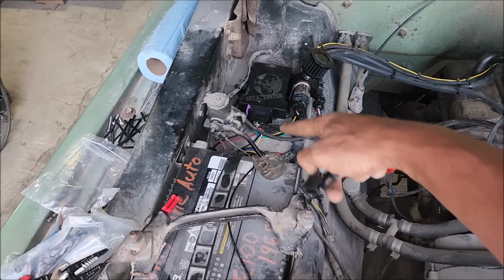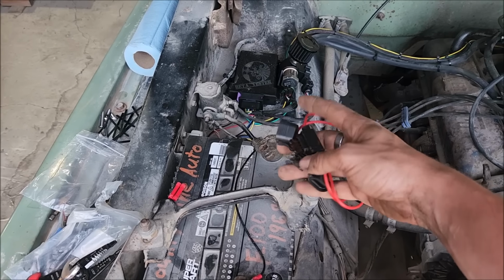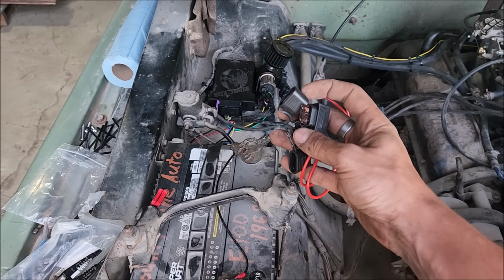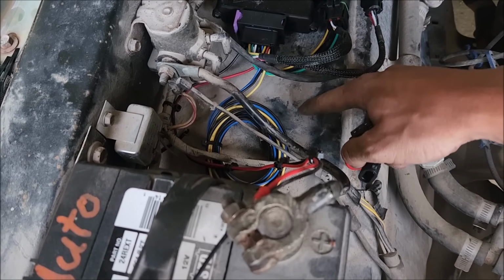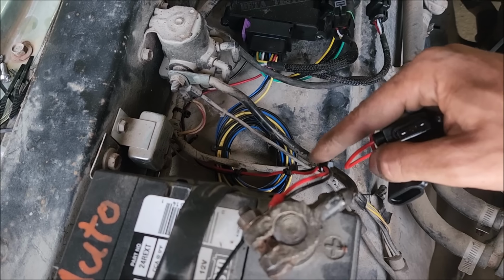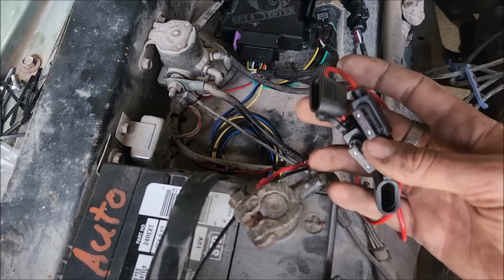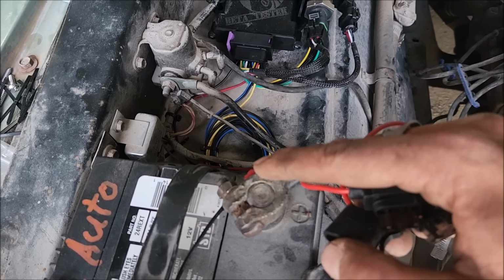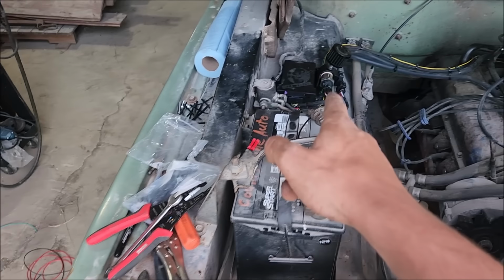So they'd be as close as possible to the ignition source, as close as possible to the battery source. That's why we don't have them tagged into our loom, because technically you need to clip them and use our supplied splicers and put them in. Now, our circuit is protected, but the reason for this is if this red wire were to get nicked somewhere and it were to be grounding to, say, the fender, basically it would be a dead short from the battery to the fender, and it could cause a fire. So again, when using the fuses, you want them as close to the power source as possible, and that's why they're not attached to our loom, so you can cut our loom to the size that you want.